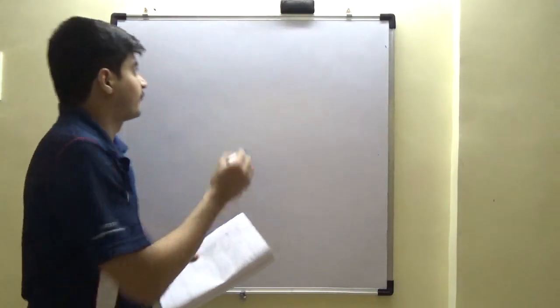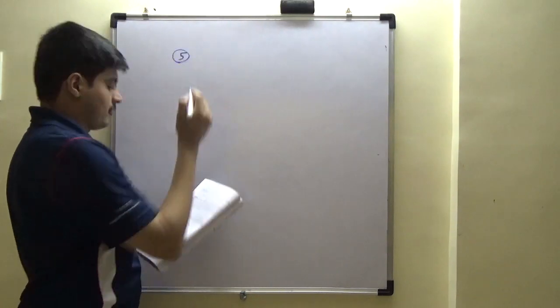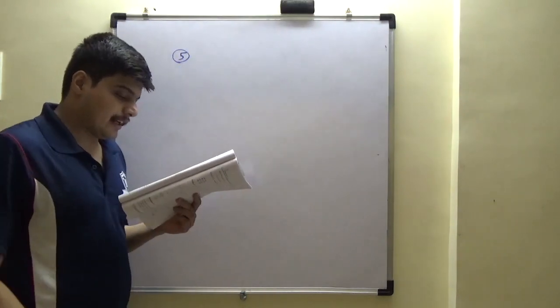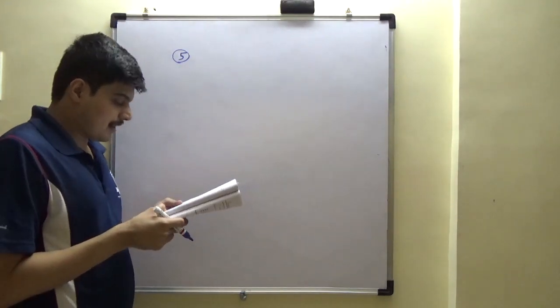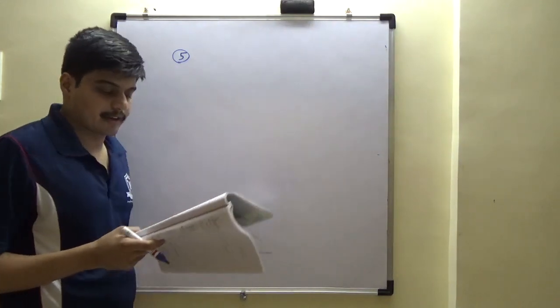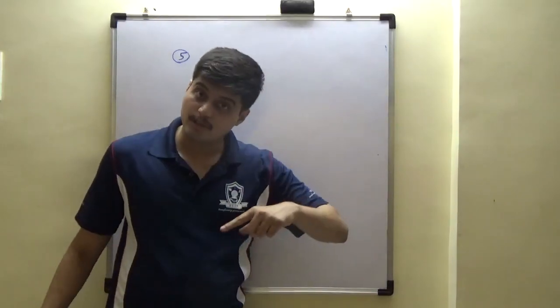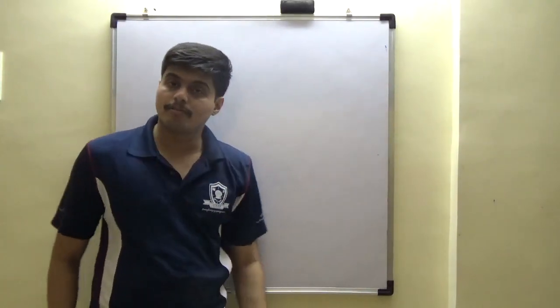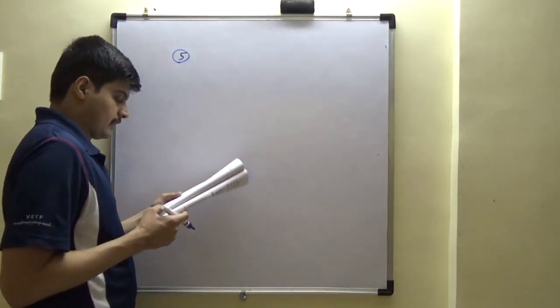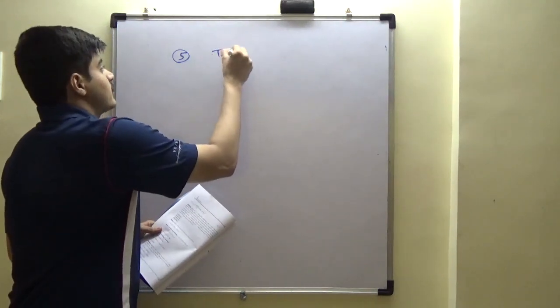It's an extremely close question, as we say, right? Question number 5. The inlet stagnation temperature of a single axial compressor is 300 Kelvin. What does single mean? Only one stage, rotor and stator. Undergraduate simplification, series of blades are not considered. So T01 is 300.